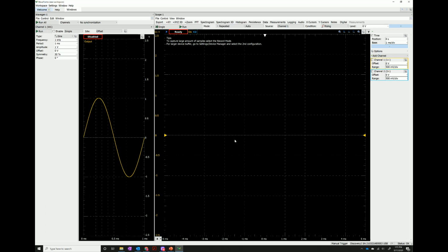If we come over to our scope and we click Run, we'll see that our scope channel is currently measuring relatively constant 0 volts. This is because our Wavegen is showing the preview of our signal here. It's the preview of what we will be sending, but we haven't actually started sending this on our waveform channel because we haven't selected Run on the waveform yet.